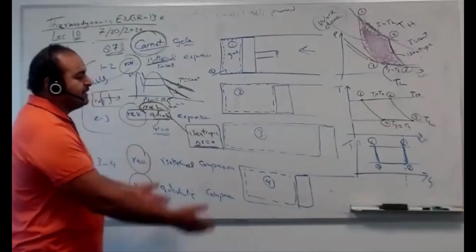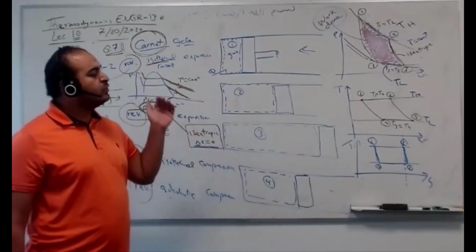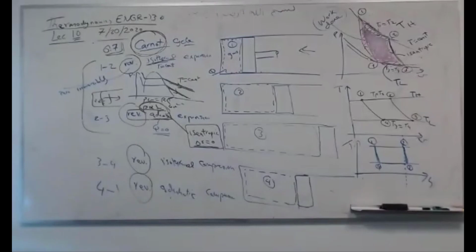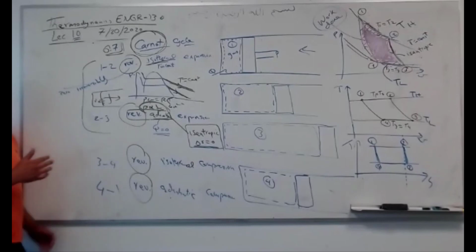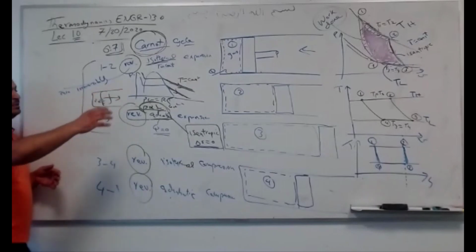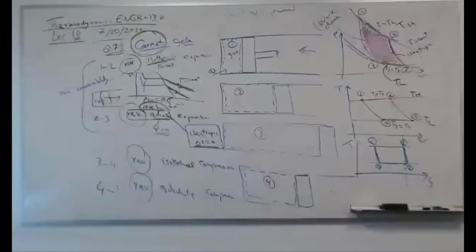And we're going to draw the whole steam table in terms of the TS diagram. So we plotted for PV, we plotted for TS, TV. It's very similar to what we did before. The more you draw, the more you understand the physics to redraw it in a curve, it's better for you to use the table. If you are in the very left, use compressed liquid. If you are in the middle, saturated mixture. If you are superheated, use the superheated table. So you know from where the state is, either from the steam table or even the ideal gas law. Okay, guys? We are done now. Do you have any questions, guys?